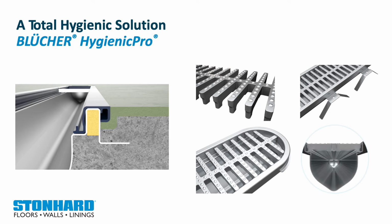The connection between this Blücher Hygienic Pro drain with our Stonhard mortar floor system is secured due to the details in the strong and completely filled edge of the drain. Because of water temperatures, stainless steel tends to expand and shrink, of course. These round edges help to prevent damage to the floors. There is far less tension between the drain and the floor than in case of a square-edged drain. The Hygienic Pro is even designed to reduce the amount of water that is needed.